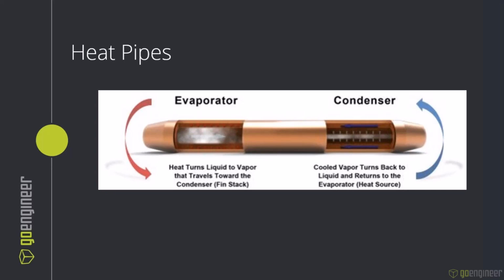They're really very capable tools. Heat pipes transfer heat from a hot surface to a cool surface, and they can have heat fluxes anywhere from 10 watts per centimeter squared up to 20 kilowatts per centimeter squared. So it's really very efficient in the right conditions, and used a lot of times in high power electronics. Those of you who are familiar with CFD may know that this is a computationally very expensive process, to capture the evaporation, the condensation, and the transport in a porous media. It's all very expensive.